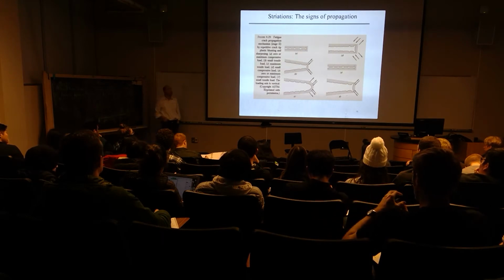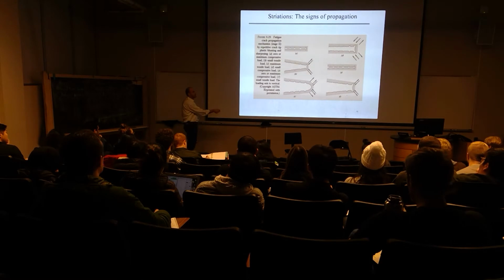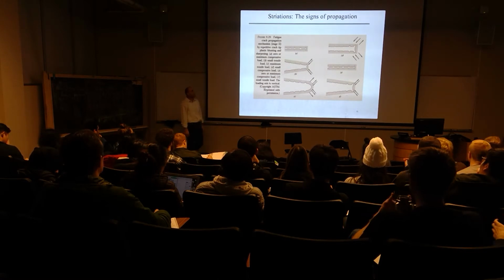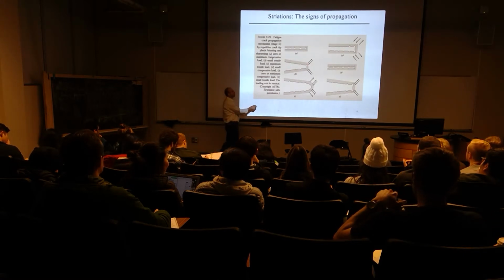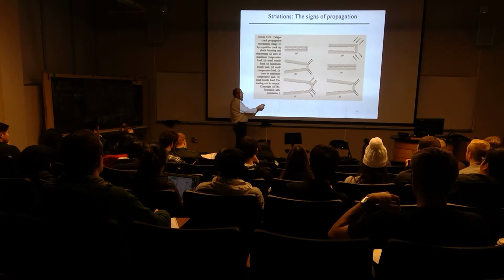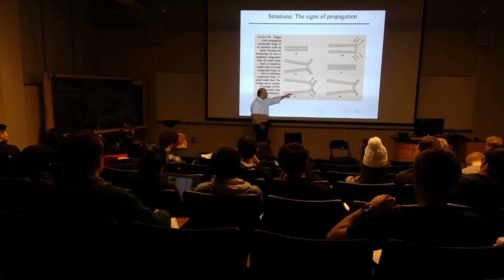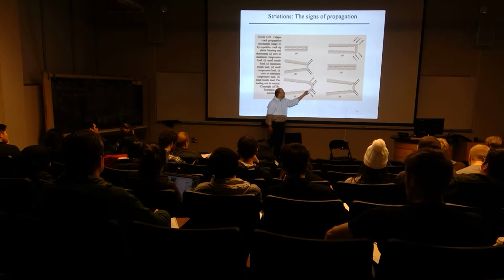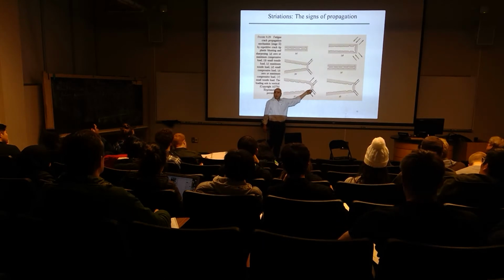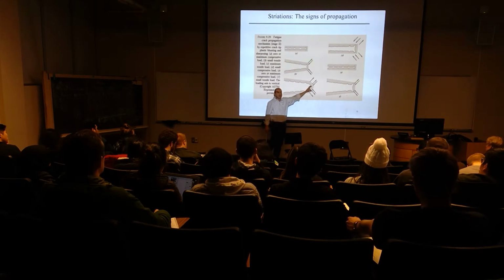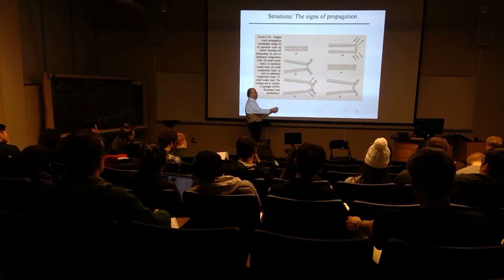And that will occur preferentially along the planes of maximum shear stress. So that will occur on these 45-degree shear angles that are simply defined by Mohr's circle, right? That will allow new surface area to generate specifically on those diagonals, those 45-degree orientations with respect to the plane of the crack. And eventually the crack will open up wide enough that it starts to enable new surface area development just by the continued plastic deformation process. The crack ovalizes, and the amount of ovalization is going to be a function of the amount of ductility.